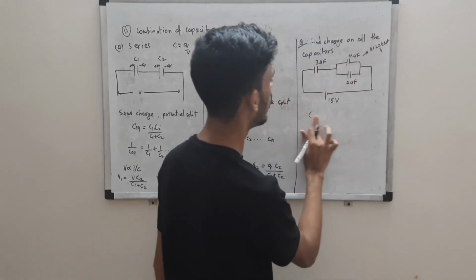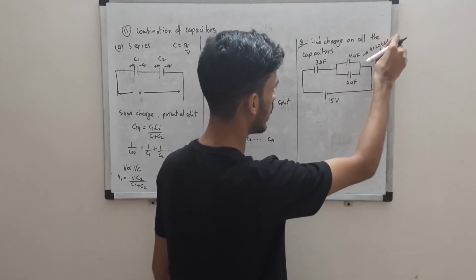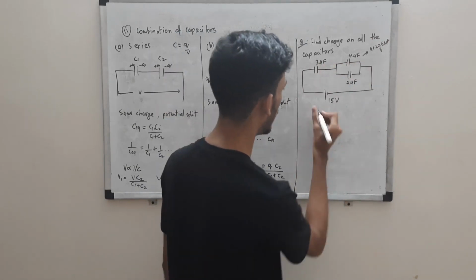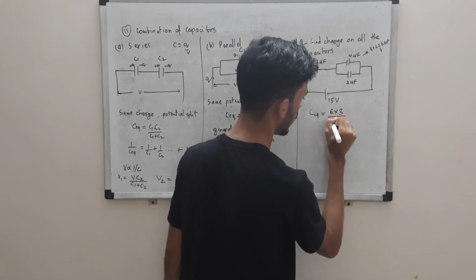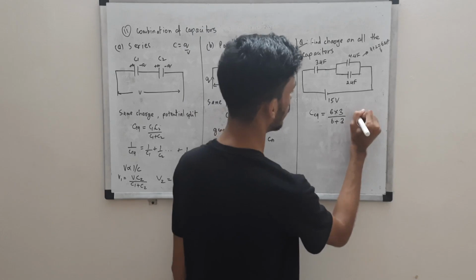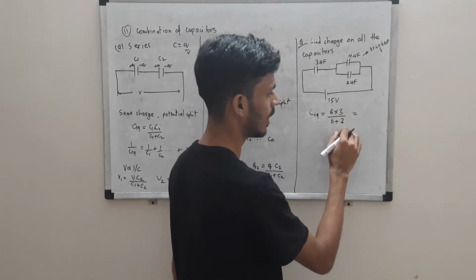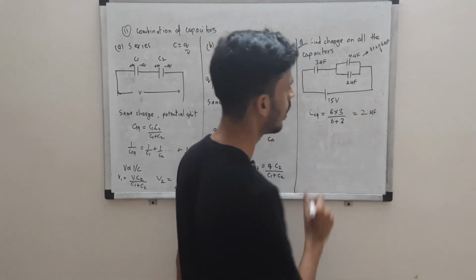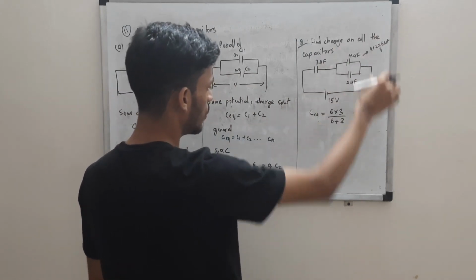microfarad, right? And now this 6 is over here, you can replace this entire thing with a 6 microfarad capacitor. So this 6 and 3 are in series. Series: 6 times 3 upon 6 plus 3. 6 and 3 in series will give you 2. Remember, you can remember it that way. It's a direct result. 6 3 is 18, this is 9, 9 2 is, right? So 2 microfarad. This is your net capacity. First we considered this in parallel and then those two in series.